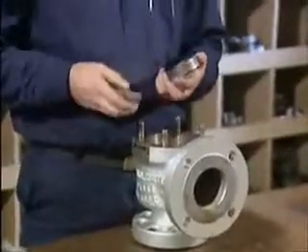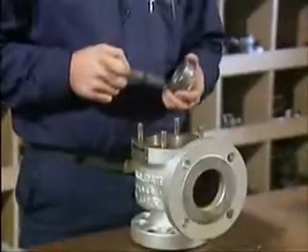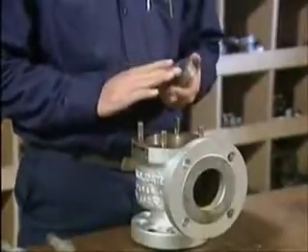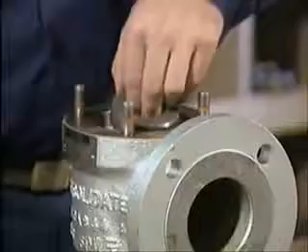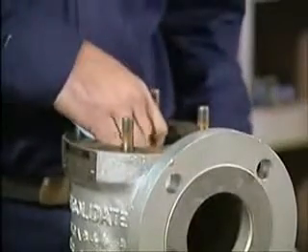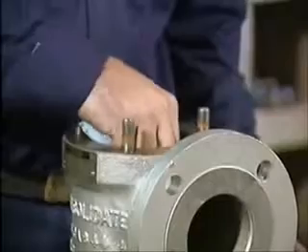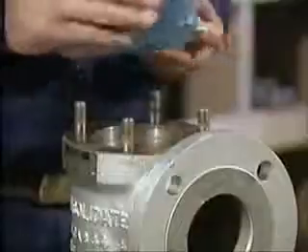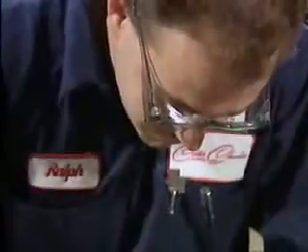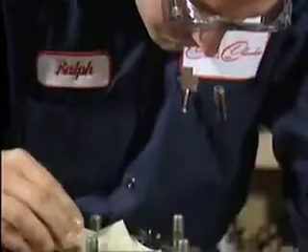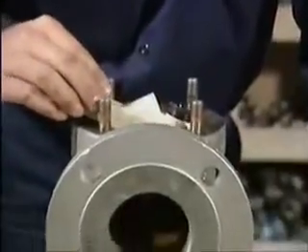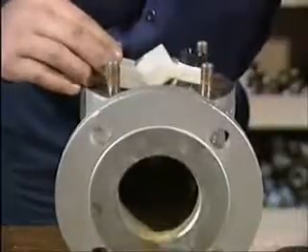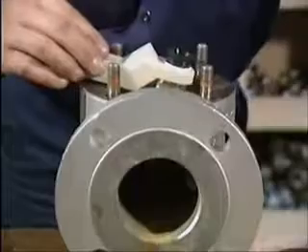If the damage isn't severe, you can probably restore the surface of the seat by lapping. As with the disc, you must use the appropriate lapping method for the shape of the part. When you're done lapping, clean all traces of lapping compound off the valve seat and all other internal surfaces of the valve. Then wipe any remaining residue off with a clean cloth. Now, use a light or bluing to inspect the clean seat for any nicks or uneven spots. If you find such imperfections, you'll need to repeat the lapping process until the surface is smooth and even.